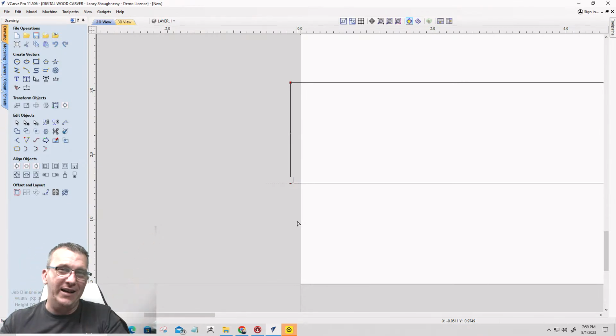If you tell it to move left, right, and when I say tell it, I mean drag it. You drag your mouse and you stop moving. Once you move in the direction you want it to go, just stop moving, keep the left mouse button held down, and type in your value and hit enter, and it'll finish the movement to the distance you specify. Okay?